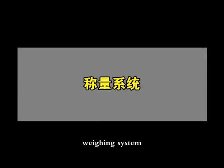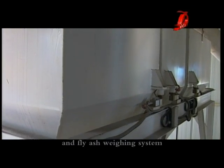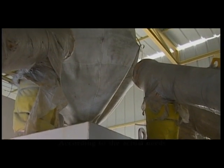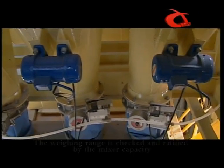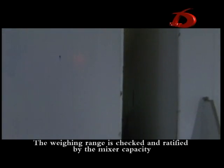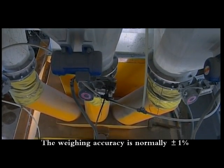Weighing system. The weighing of powder generally has 2 kinds: cement weighing system and fly ash weighing system. According to the actual needs, it can use cement and fly ash cumulative weighing or individual weighing. The weighing range is checked and ratified by the mixer capacity. The weighing accuracy is normally of plus or minus 1% error.